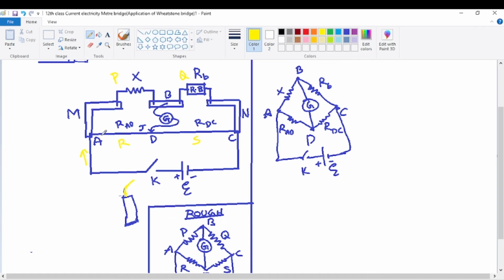So finally, as it is moved like this, the deflection will go on decreasing. Initially the potential difference between A and B is 100 minus 50, which is 50 volts. Next we'll go to 90 volts. 90 minus 50 is 40. Earlier the potential difference between A and B was 50, with the jockey at A. Now when the jockey is somewhere beyond A at the 90 volts potential point, the potential difference between jockey and B will be 90 minus 50, which is 40.